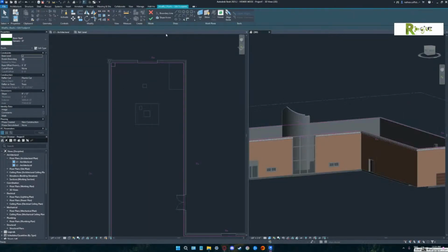Okay. Then if you do an offset, which looks a little different, that one right there. And we want to do an offset by, let's just say, 2 feet just to get it outside the wall. Okay. And then turn copy off. And if you go down, don't click, hover over one of the purple lines. Do your middle wheel to get you back in the frame. Now take it to the outside and then hit tab.